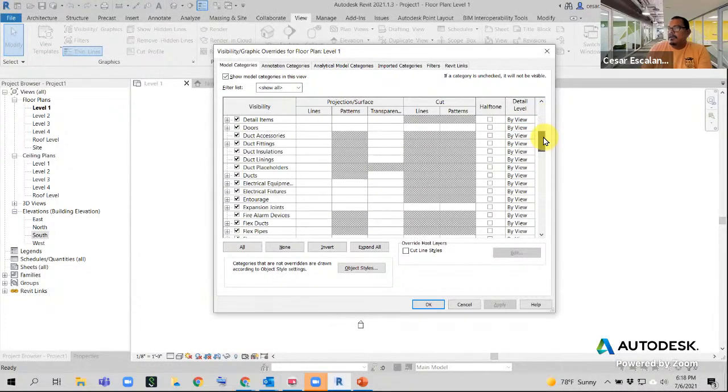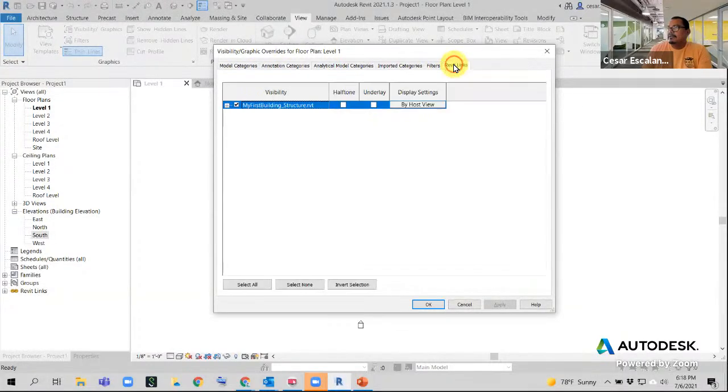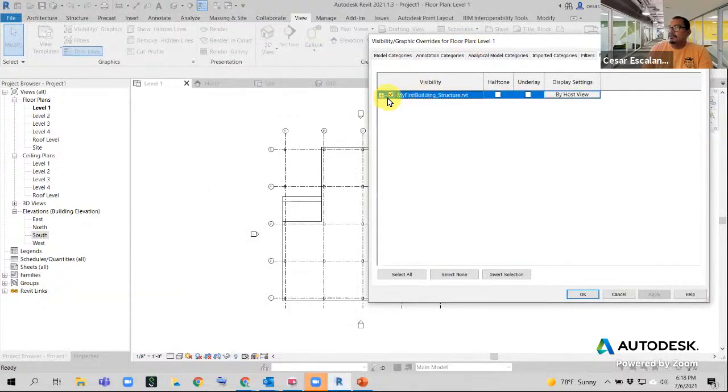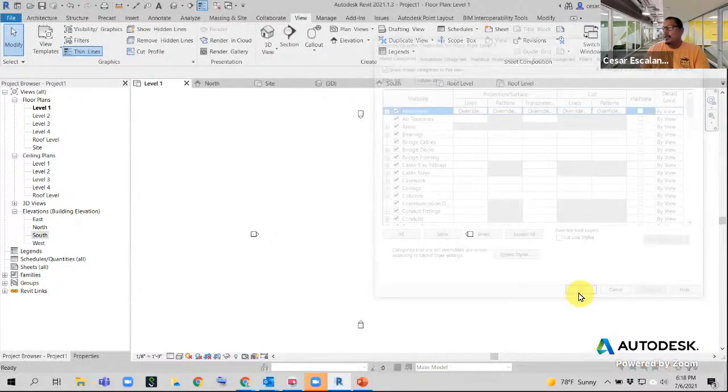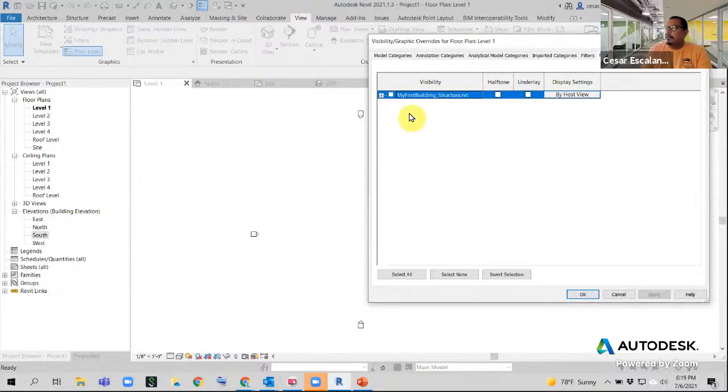We're going to go to the Revit links. This tab wasn't available to us before. This link only becomes visible to you when you link objects. And this is a way to turn on and off a link in the project. So if you click this checkbox here, that switches off the link in the model. Again, visibility graphics, Revit. I'm going to enable it again.